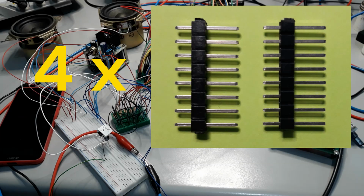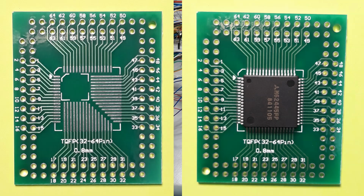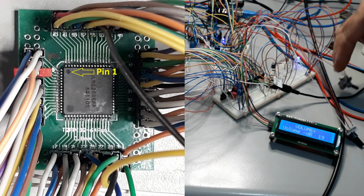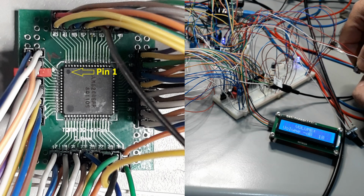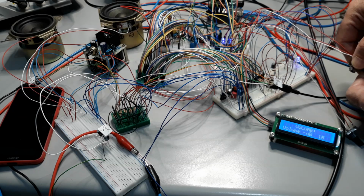This type of package discourages many enthusiasts, since it requires the design of a dedicated printed circuit board. That concern is completely understandable. As is often the case on this channel, we work around this limitation by using a small adapter board. This board mirrors all the pins of the integrated circuit onto the breadboard, allowing direct pin-by-pin access.